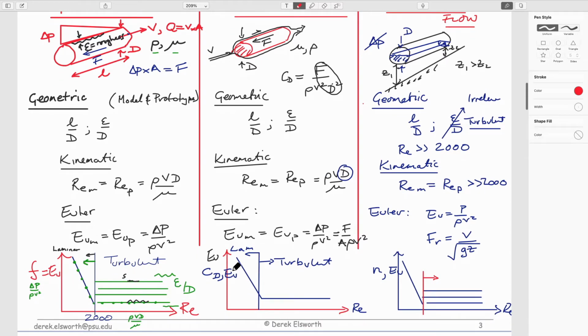For laminar flow, the overriding effect is viscosity, and it's the viscous drag on the side that makes the main component of force. And as velocities go up, viscosity becomes a trivial component of this, and it's the stagnation of fluid hitting the front of this closed container that is really the force.